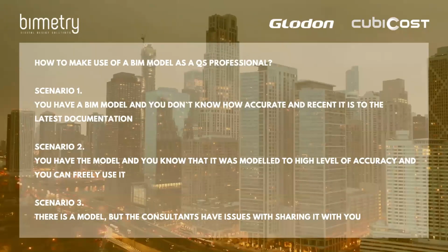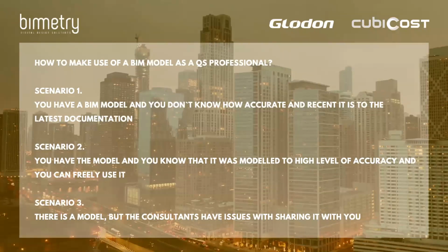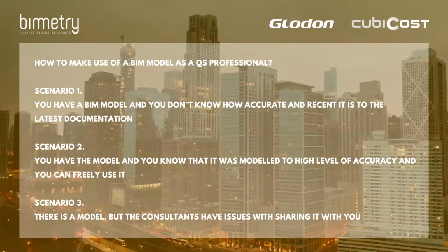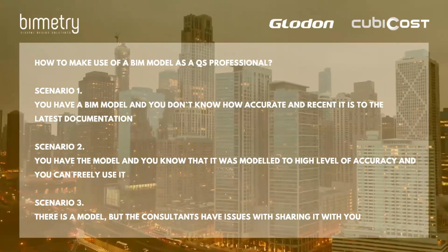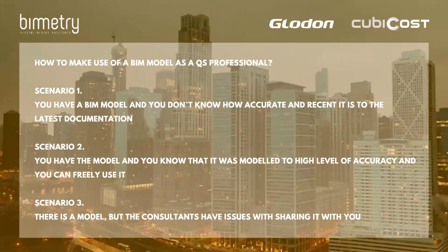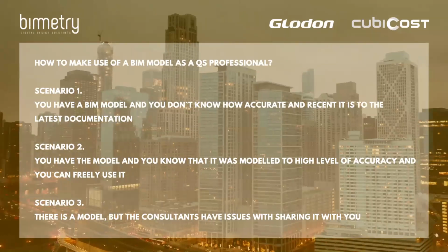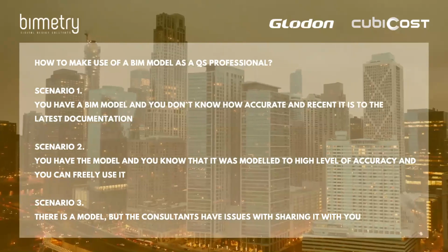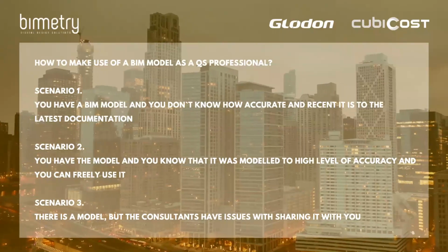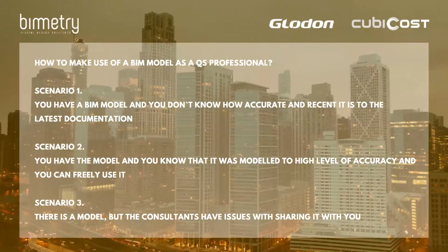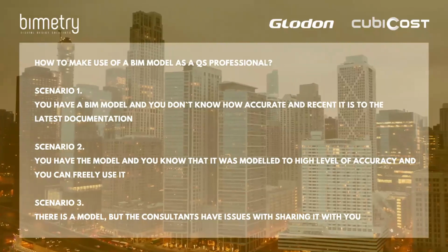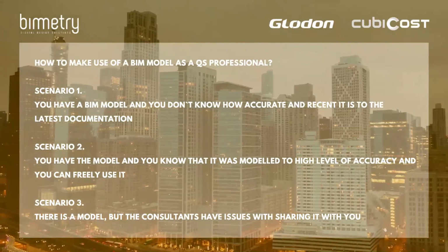But there is a workaround to this, as you don't need their content except for the quantities from it. You just create a Cubic Cost file by importing their Revit model, or you can just directly ask them to import their BIM model into your Cubic Cost license. This is not anymore a native Revit format, so the consultant's IP and copyrights are protected, and at the same time, you have managed to do your job. So this is all a matter of discussion. Just make sure that when a consultant doesn't want to share their model, you ask for the reason behind it.